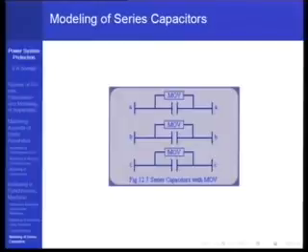Actually, when the high fault current flows through this capacitor, then an over voltage develops across it. Because of that over voltage, this MOV will conduct. It's a varistor, it's a ZnO varistor. So as the voltage across it increases, it's a nonlinear resistor, so its resistance drops down.